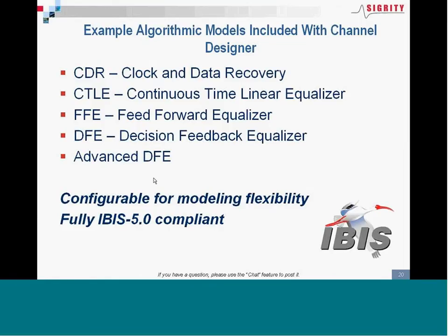The intent there is to allow you to very quickly do feasibility studies like you saw. Also, if you find a case where you need a model for a particular SerDes that's not available yet, the intent is that you can program one of Sigrity's models, hopefully, to mimic that device fairly closely so you can do some of your initial simulations. Okay, again, fully IBIS 5.0 compliant.